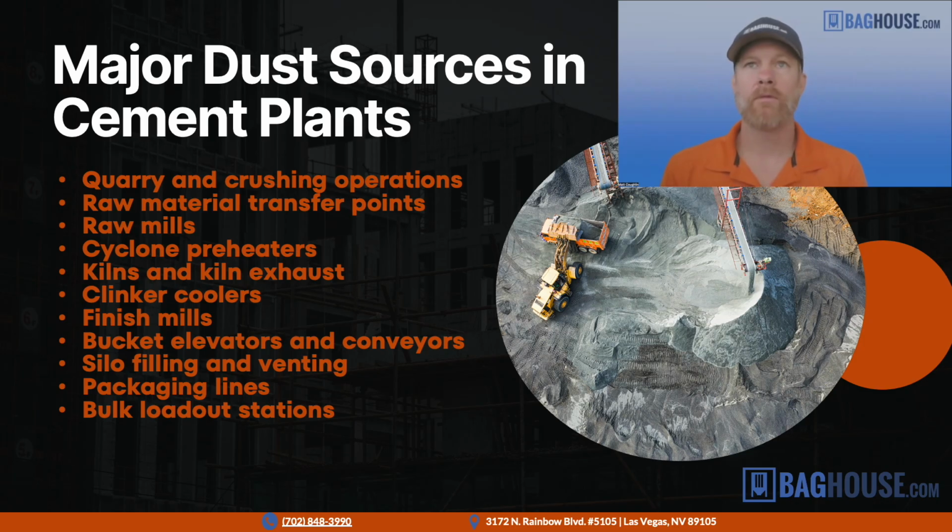It's very common to see a dust collection system going to those points, which is just a duct, like a straw into the box, without much consideration of the vent design at that point, which is actually critical, because once dust escapes the enclosure and becomes airborne, it's much more difficult to deal with. It requires a lot more energy to collect and filter dust out of a large volume than it does to collect dust out of an enclosed area. The airflow requirements go through the roof. So each one of these points, similar approaches.